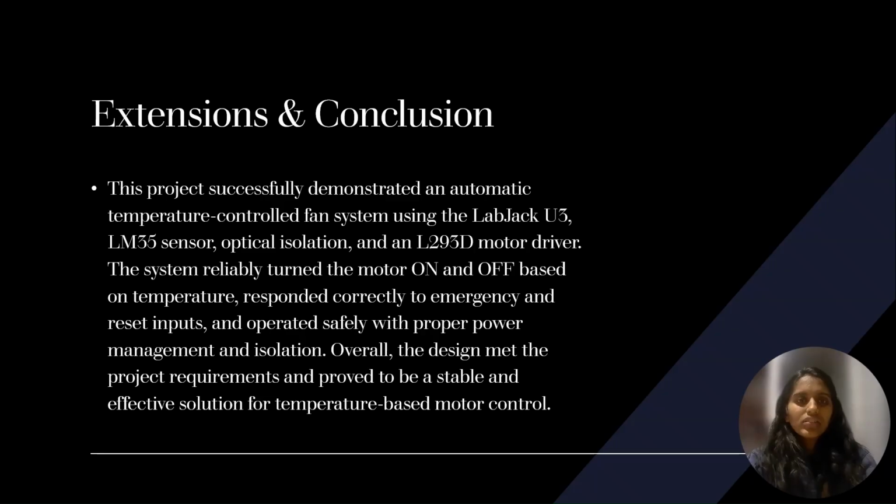And then the final conclusion slide. So to conclude, our project successfully created a fully working automatic temperature controlled fan system. We met all the design requirements: accurate temperature sensing, automatic fan activation, emergency stop and reset features, isolation between lab jack and the motor, and stable 12-volt motor control using the L293D. The system reacted smoothly to temperature changes and worked safely without damaging any component.